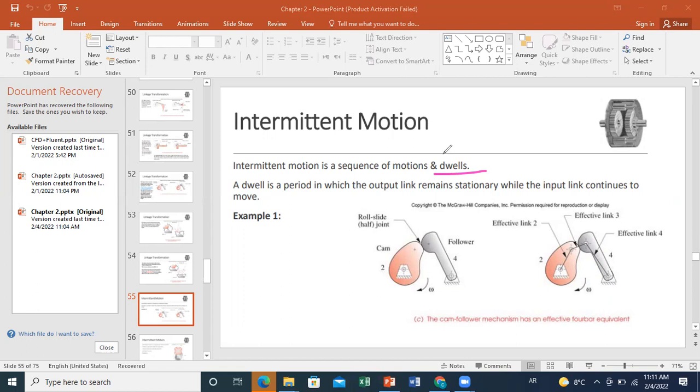I have several possibilities. The first strategy is to use a cam follower system. How can I induce a dwell for my follower? The idea is to understand how the cam follower operates. The operation of the cam follower system relies on the variation of this distance. Because for the cam you can provide any profile, and this profile is characterized by a changing distance between the fixed point of rotation and the different points of your cam.